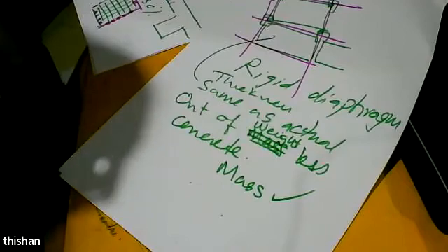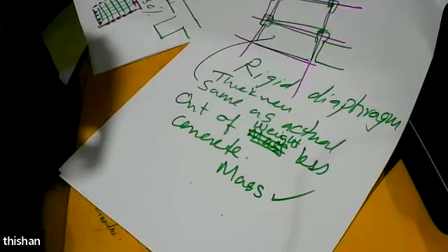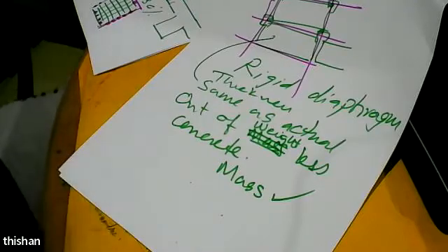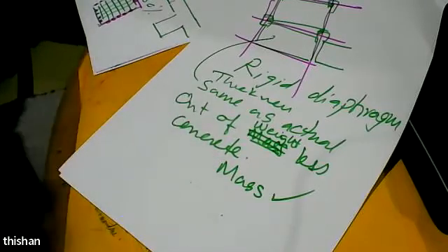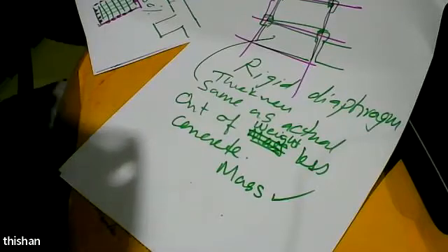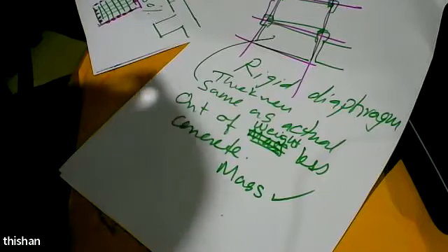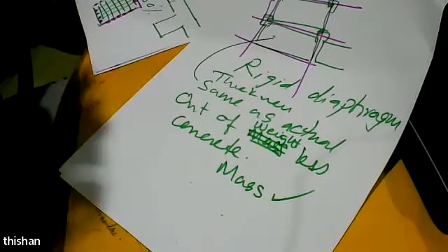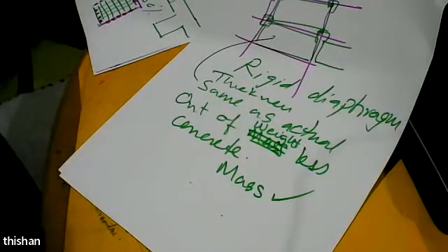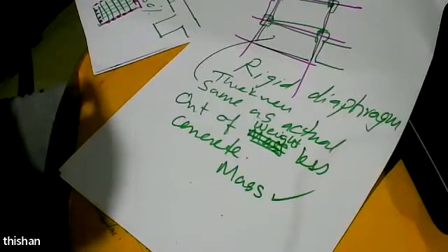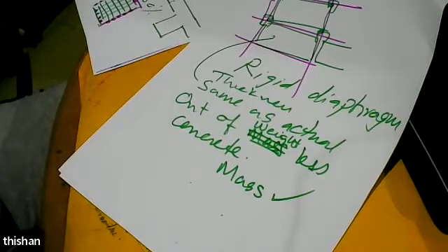We need a mass there because there is a slab. Slab has a mass, and mass is based on the actual thickness of it. So because of that reason, you have to always think and think. When you are making a mathematical model, always distinguish between mass and weight. And for every element, you have to make sure that you have got the weight right, because weight will contribute to the vertical load and also vertical load resistance. Whereas the mass is more important when you are considering the vibration characteristics of the structure, and vibrations will ensure that the building will shake laterally in X direction and Y direction.